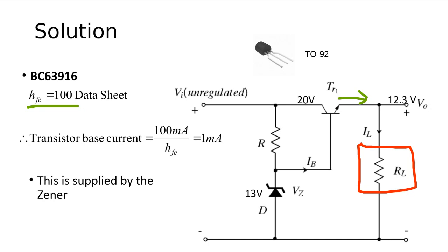At this point, the supply is going to go directly to ground. If you short circuit, the load current goes up drastically. In theory, it's going to go to infinity. Of course, the system will handle the maximum that the devices can handle.